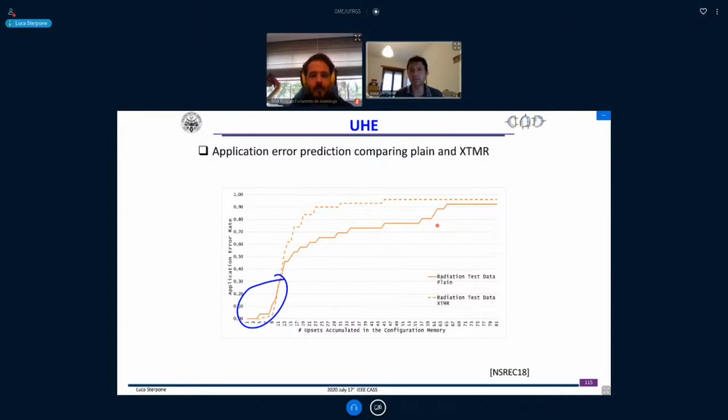evaluate the clock domains and, for example, the clock resources inside the FPGA, because you can adopt clock dividers, and also multiply. You can have a PLL to increase the clock frequency. It will be interesting with finite state machines to use this type of counters or finite state machine to evaluate the impact on the clock.